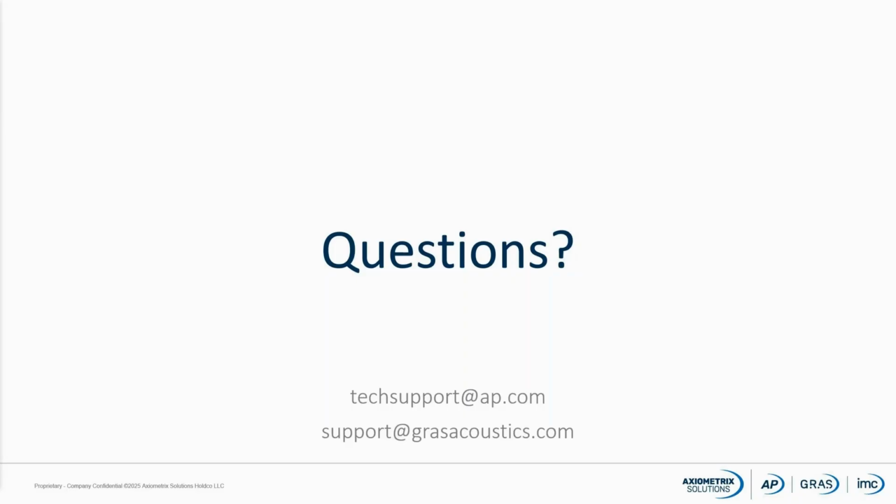So we have some questions already. Someone has asked, how is the value of 10 millivolts per Pascal determined? In APx, our default value is 10 millivolts per Pascal, so I was just using our default. The microphones I'm using were, I think, 9.5 or something like that. So it was close enough that I could just demonstrate how the measurements work. But for your own sensitivity, you would obviously check the data sheet for the microphones that you're using.